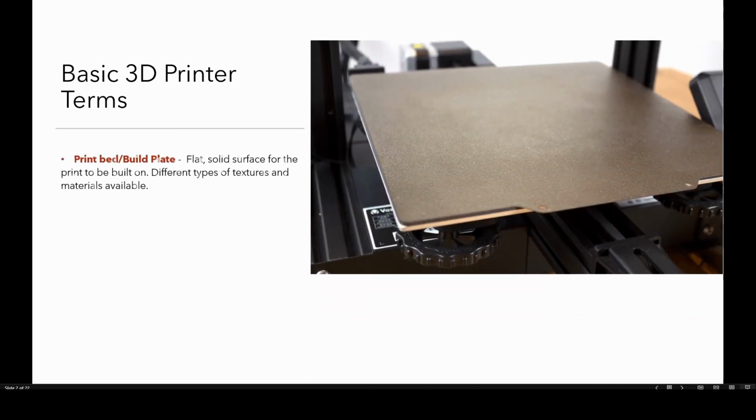It is the platform for your 3D printer to print on. The main goal of the print bed is to provide adhesion so that the 3D printed object sticks onto the bed until you take it off. There are different types of swappable print beds that you can put on for various use cases. One of the most common types of plates are PEI that are all around good, but you can also get some unique ones like glass print beds, which guarantee a smooth finish on the bottom.